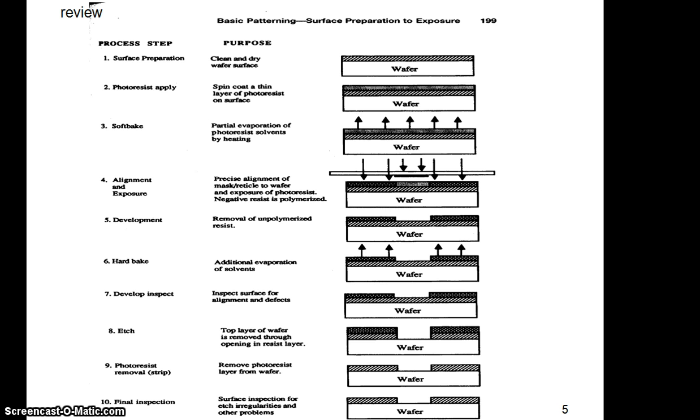Then alignment and exposure on the lithography machine. We use contact printing, proximity printing, or projection printing for transferring the pattern from the mask to the silicon wafer.